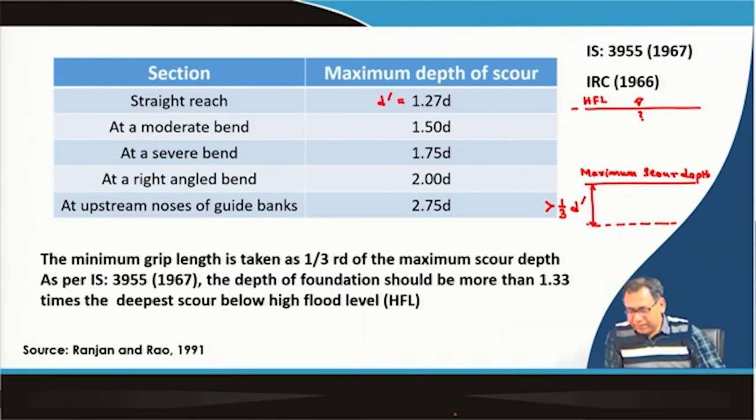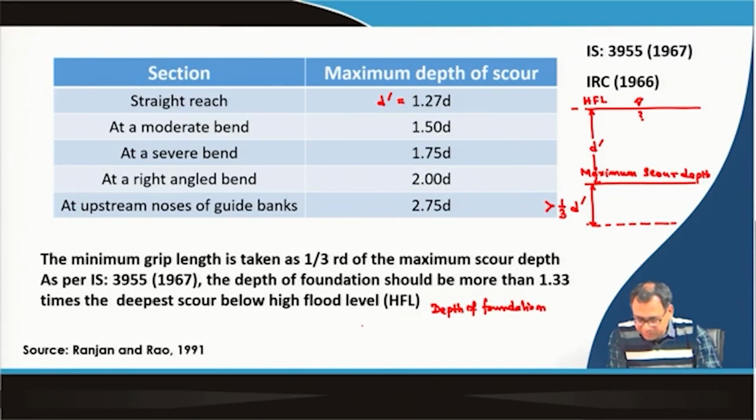So if this is the maximum scour depth, d dash from the high flood level, the total depth of foundation should be greater than d dash plus 1/3 of d dash.